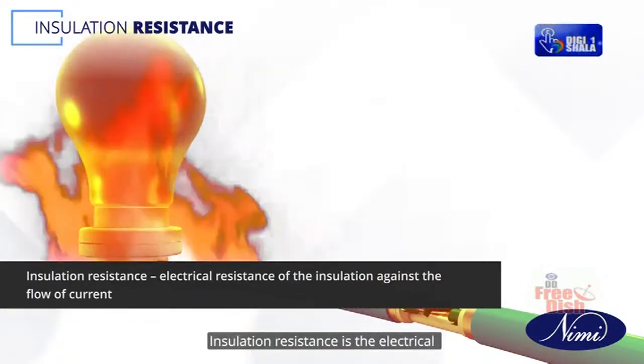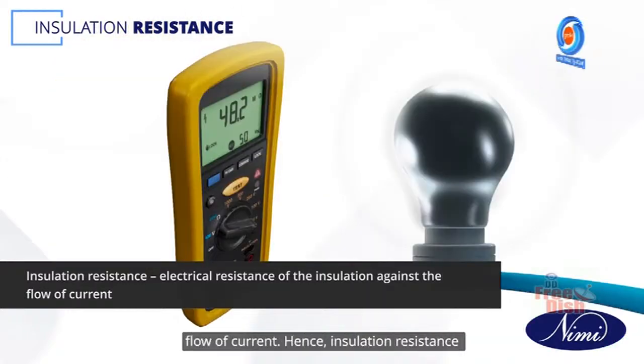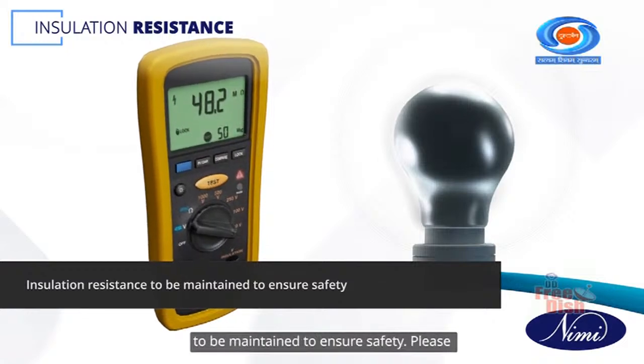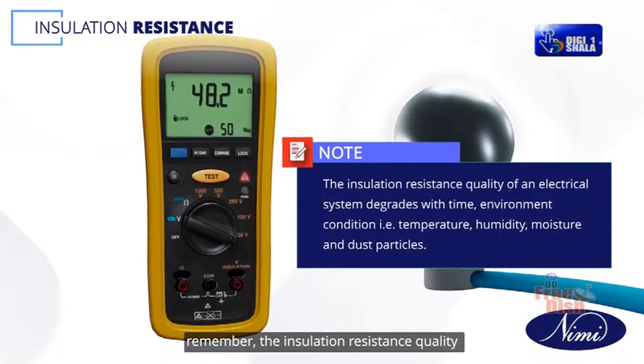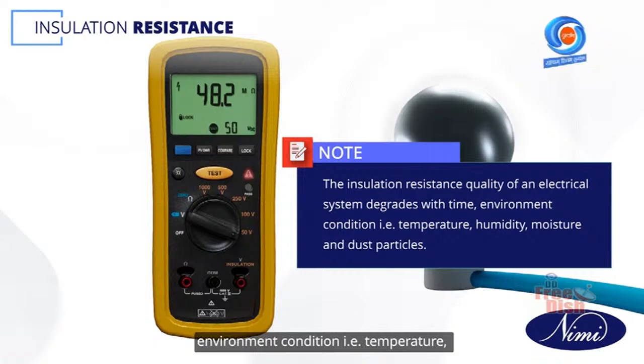Insulation resistance is the electrical resistance of the insulation against the flow of current. Hence, insulation resistance must be maintained to ensure safety. Please remember, the insulation resistance quality of an electrical system degrades with time and environmental conditions, that is, temperature, humidity, moisture, and dust particles.